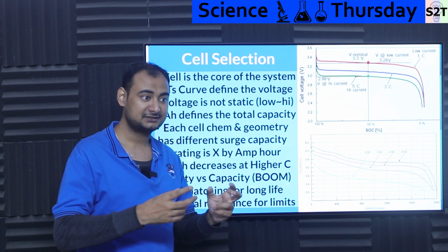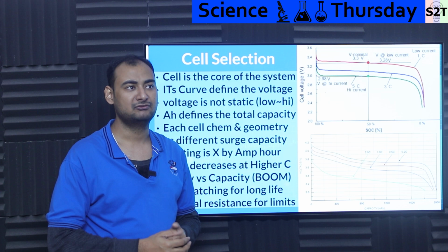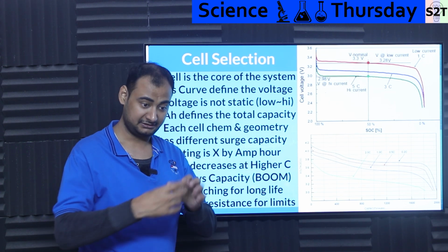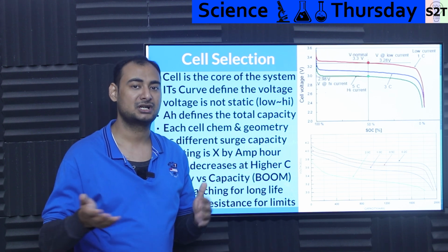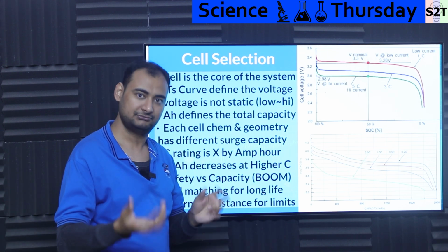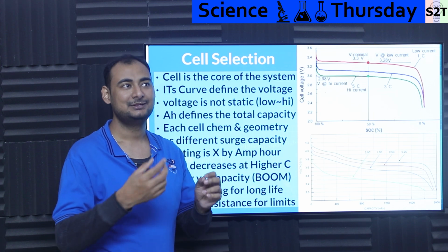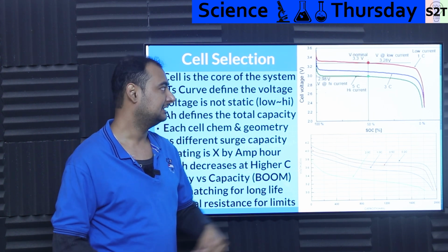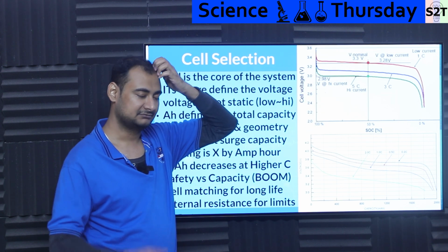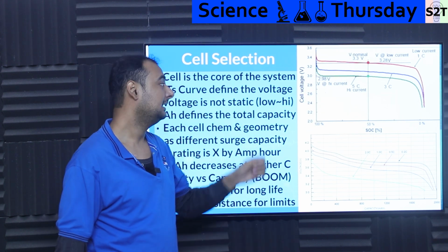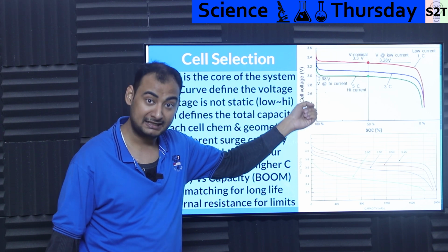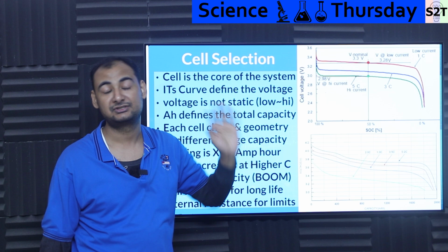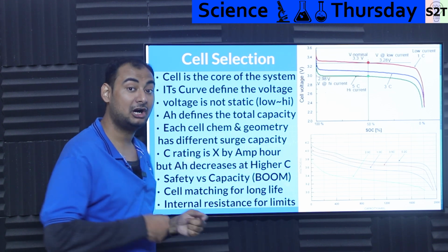For example, a power bank that is designed for 15 watts is very easy to make, very cheap. But consider a power bank in the same size, because you generally have a 100 watt hour limit in airlines, so you will never be able to increase that. But you want a cell that can give you power delivery of 100 watts. At that point you need high current capacities in the cell, and you have to design the circuit to manage that, not to freak out, hey, the battery voltage went to 2.98. It should not freak out on that, and you have to accommodate for that.